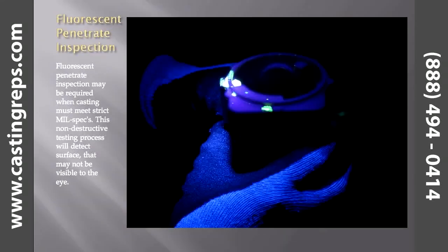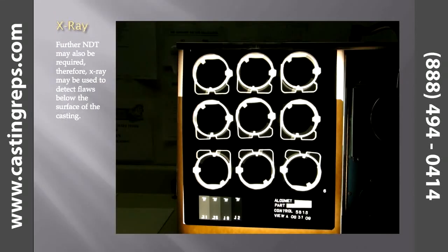Fluorescent penetrant inspection. Fluorescent penetrant inspection may be required when castings must meet strict mil specs. This non-destructive testing process will detect surface flaws that may not be visible to the eye. X-ray. Further NDT may also be required. Therefore, X-ray may be used to detect flaws below the surface of the casting.